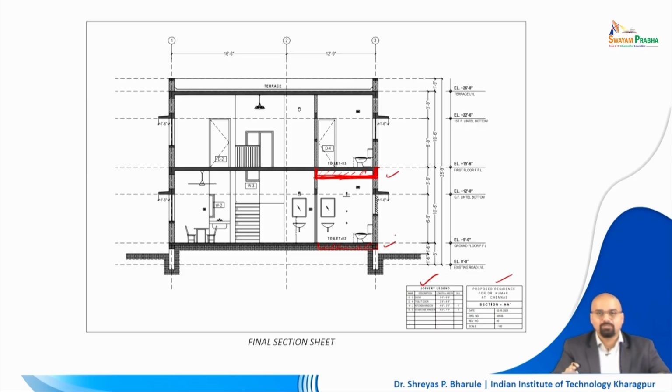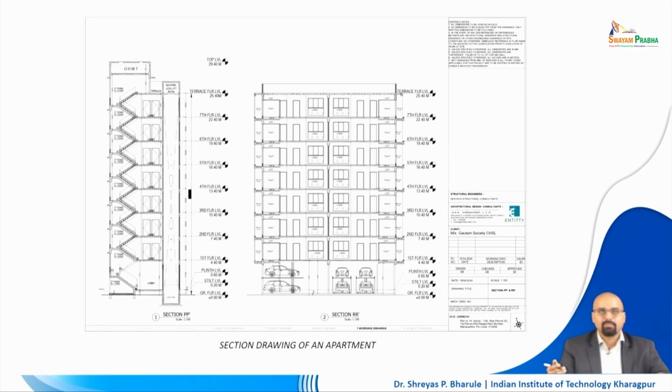That's why this is not in a complete template, right? This is the final section sheet, but this is a preliminary which is usually sent to the structural consultant, and then the structural consultant suggests amendments, right? The amendments are suggested, it will come back like this, and then once the details are incorporated, we say yes, this is a problem, this is how we will be fixing it, that we will be including the sunk slab in the drawing, and then it will be executed in the similar fashion on site, right?